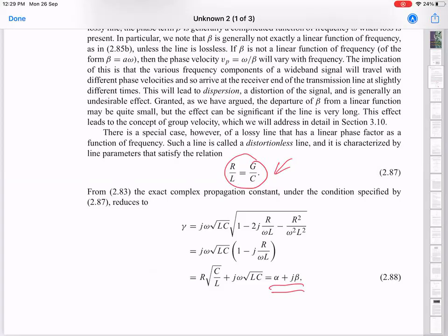I will discuss this in way more detail in a later lecture, but essentially the point I was trying to make is that if you had a perfectly lossless line going from room temperature to low temperature, then at room temperature you usually have Johnson noise or Nyquist noise associated with the components at that temperature. And if the line is lossless, then that noise will completely reach your experiment with the same intensity. That is usually incompatible with the fact that one of the reasons you often go to low temperatures is that you're trying to reduce the noise.